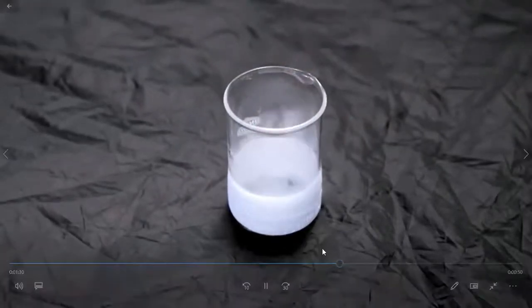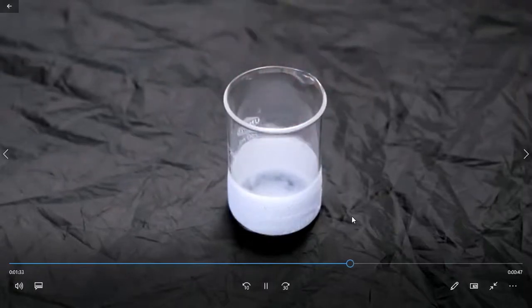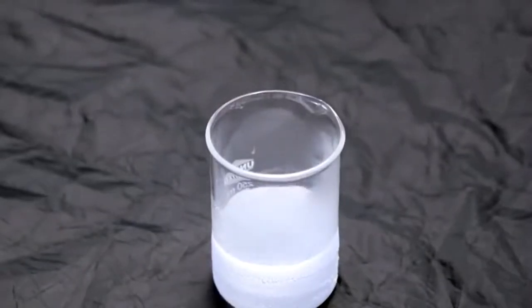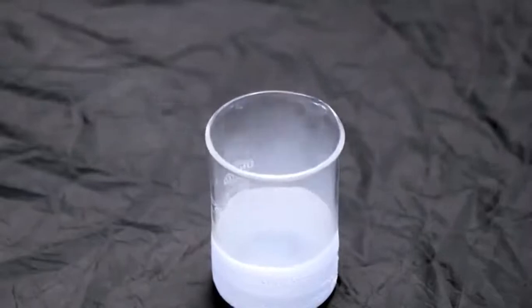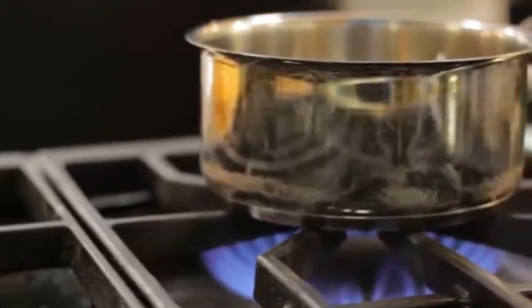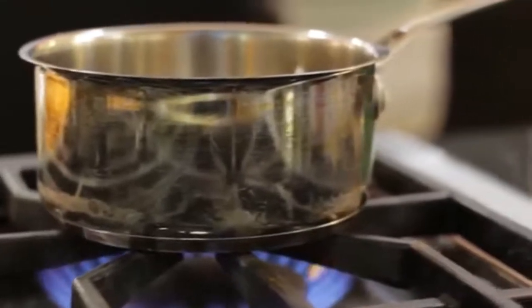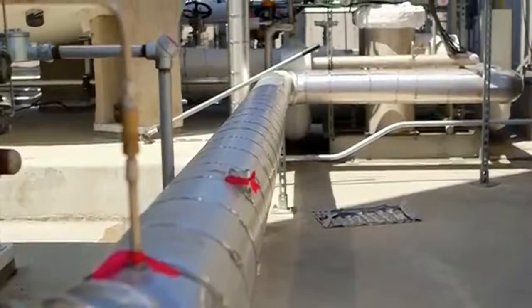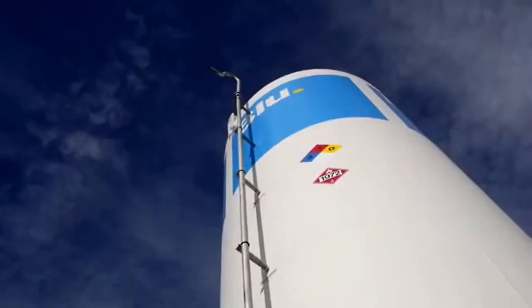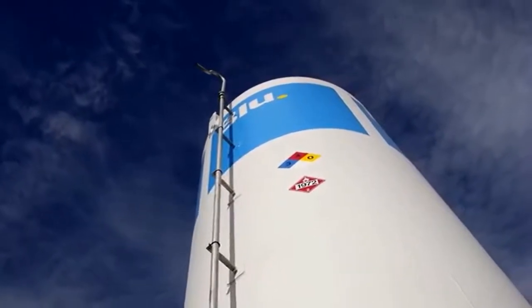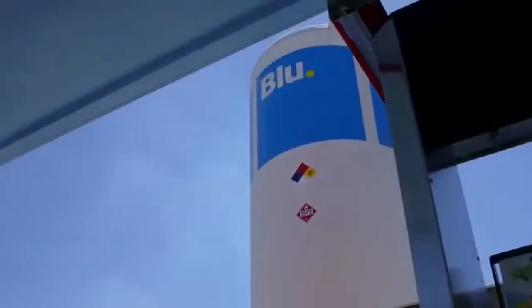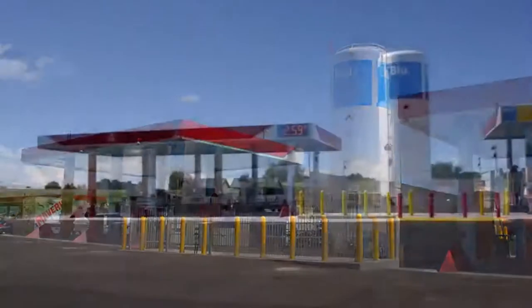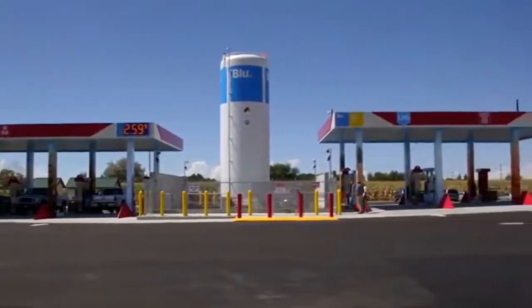...than a blaze. This is different from other gas fuels such as propane and gasoline, which are highly flammable. As LNG mixes with more air, the mixture becomes too lean to burn. This is called a lower flammable limit. Now it's important to understand that natural gas does burn. That's why it's an efficient and versatile fuel. However, for LNG to burn, it must be in a gaseous state in combination with air or oxygen. Within its storage tanks, LNG is always maintained in a liquid form, with natural gas vapor but no air above the liquid. The tanks are also well insulated and vapor tight. This means not only can oxygen not seep in, but LNG cannot seep out.